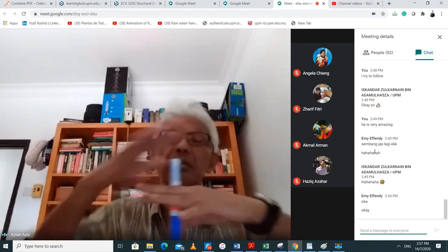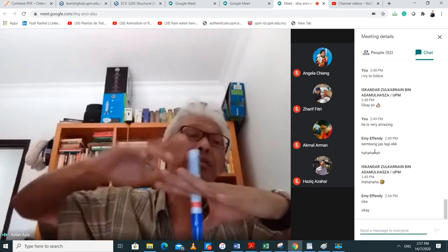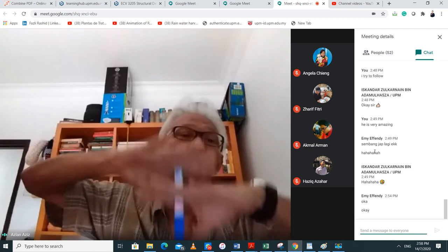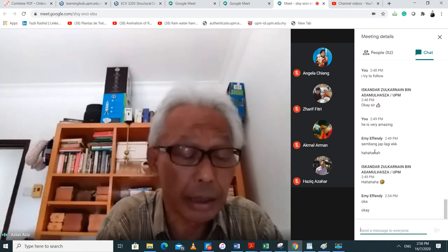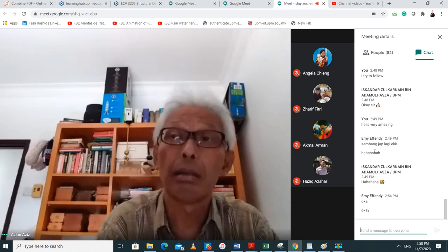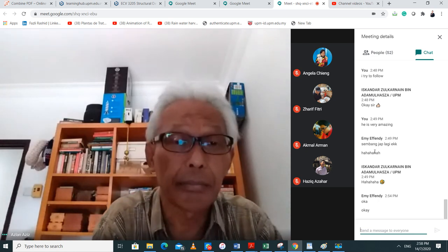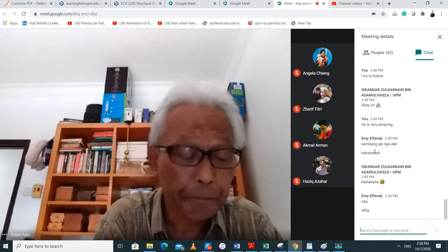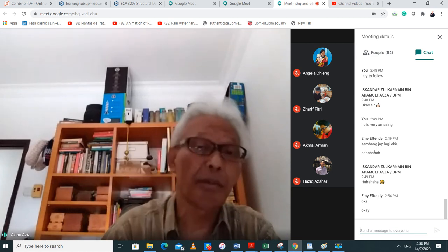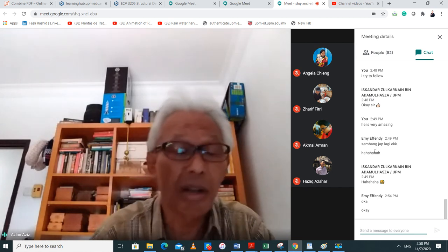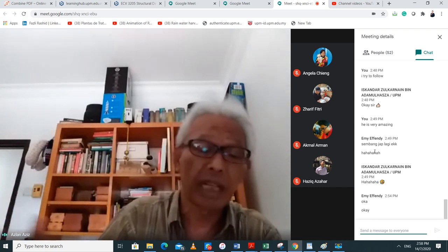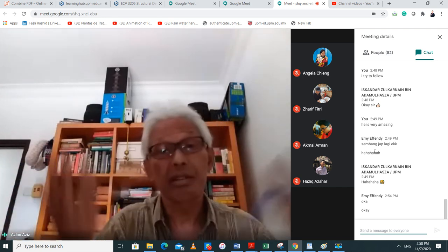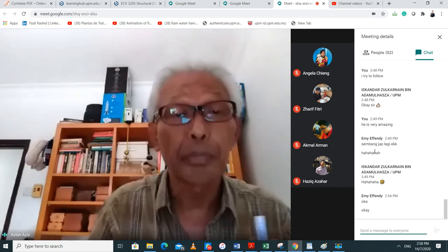See, this is in the clay, right? Here's your surface, here's the part of the pile in the clay. It pulls down the part in the soft clay. All right, but in dense sand, it's the opposite, because it's not going down there. It's dense, it's strong, so nothing happens to it. So it is still in the direction it's supposed to be.